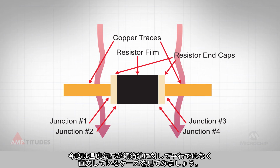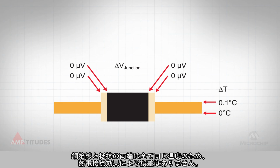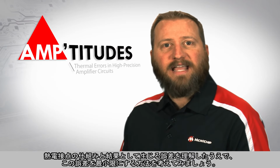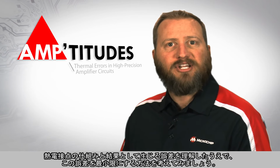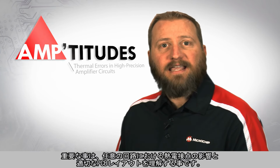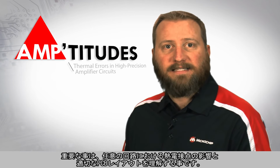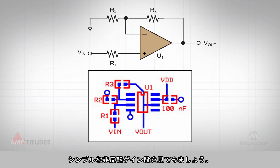Now let's examine a case in which the temperature gradient is perpendicular to the trace, as opposed to parallel, as shown in the previous case. Since the copper traces and the resistor ends are all at the same temperature, there is no error due to the thermal junctions. Now that we understand how thermal junctions work and the errors associated with them, how can we minimize these errors? The key is to understand the effects of thermal junctions on a given circuit and proper PCB layout. Let's look at a simple non-inverting gain stage.